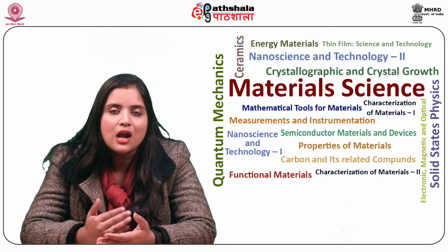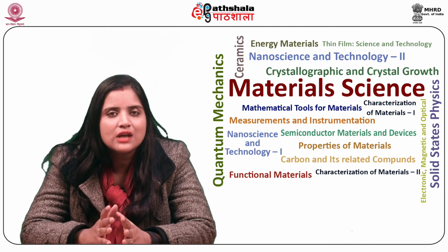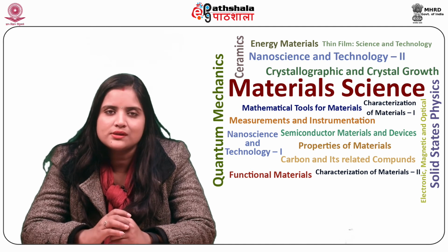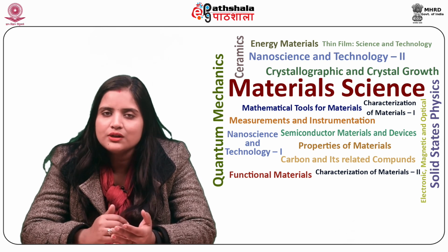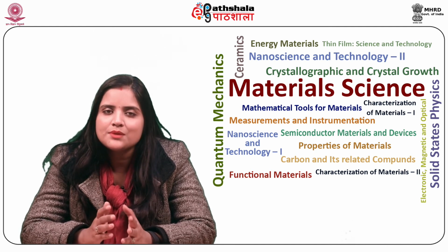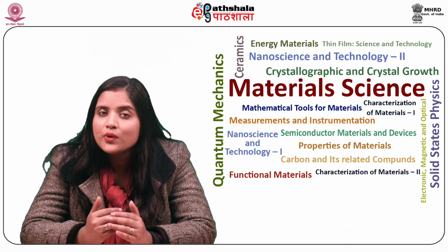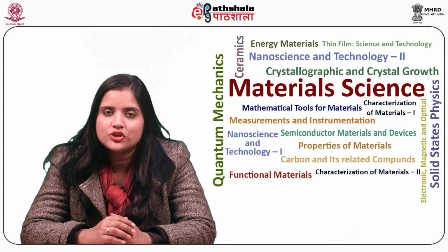Lately, semiconducting nanobelts or nanoribbons of binary oxides have been fabricated via evaporation and subsequent condensation of the precursors. Examples include the nanobelts of zinc oxide, iron oxide (Fe2O3), indium oxide, gallium oxide, cadmium oxide, etc. The precursor was used in powdered form and was vaporized inside a tubular furnace at high temperatures.